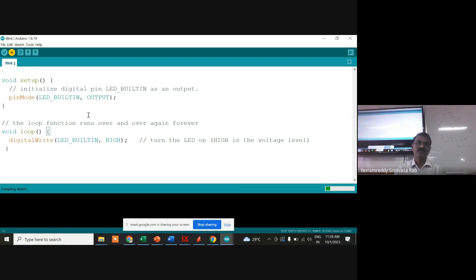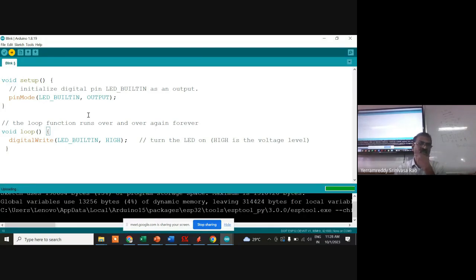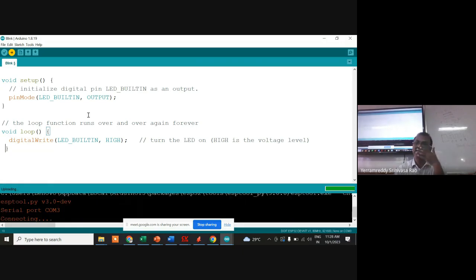Sir, the driver has been installed, but it is showing in other devices. Yes, the CH340 one did not work. Cardinal compiler is installed. Yes, that is installed, but the configuration you were showing was in ports. Right-click on it; I gave you another one, CP210. Unzip it and give its path. Some laptops, this is not working.